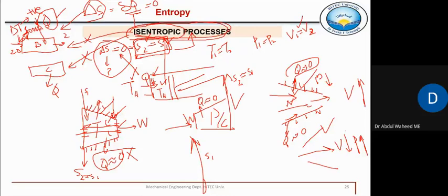We will be assuming that this process is isentropic, then we will design it, and then we shall include the frictional effects at the end, to make our mathematical calculations or design calculations easier with this assumption of isentropic. But we can never use this isentropic assumption in heat transfer devices. That should be clear. We can never use this assumption in heat transfer processes, because in a heat transfer process heat transfer is happening, so it can never be isentropic.